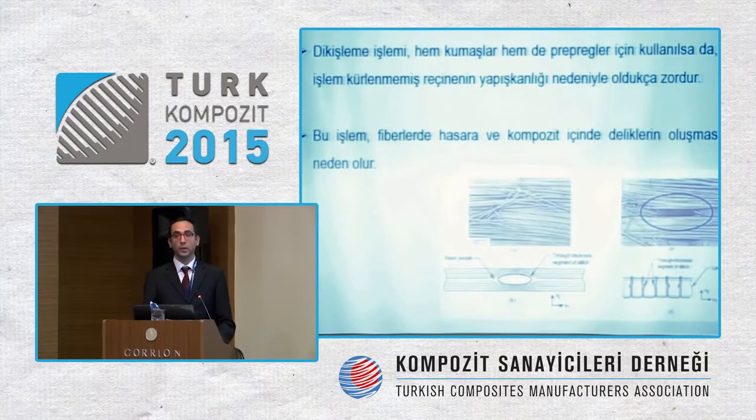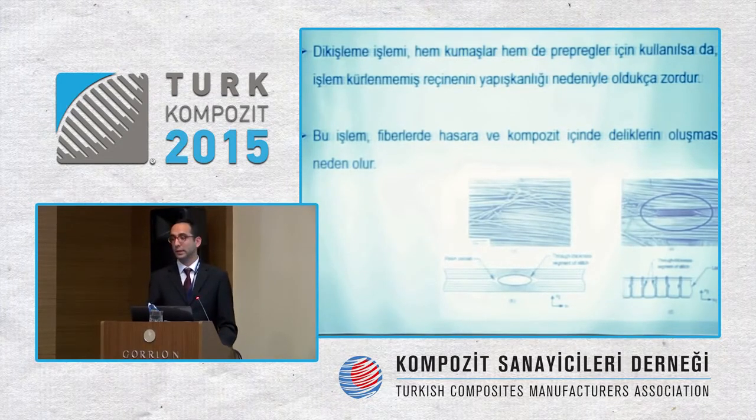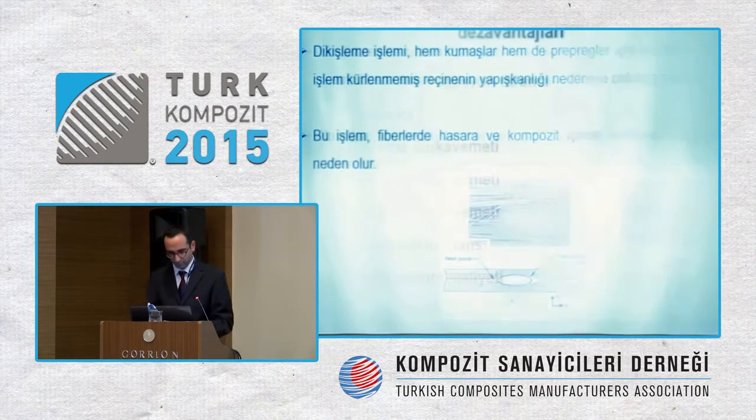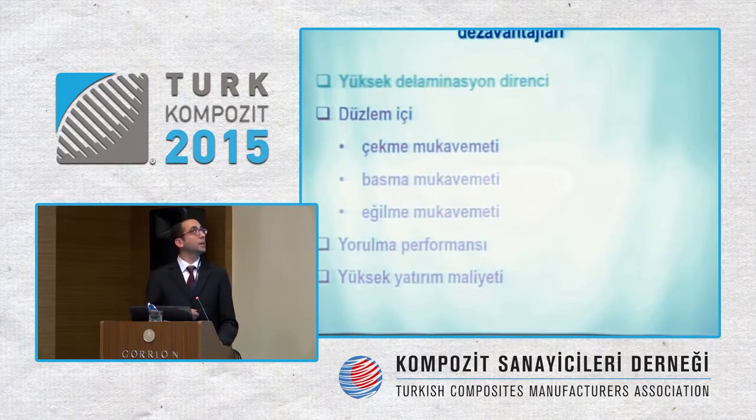And stitching is used over industrial sewing machines with high-resistance yarns, and the adhesiveness of the resins may give difficulty to the needle of the machine, and such double-way direction may damage the fiber, and we may see certain holes on the fiber.